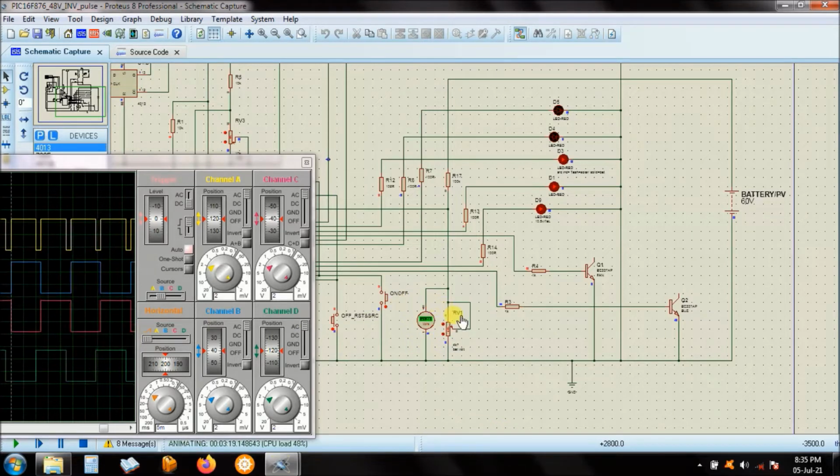Right, now I can go down here so that you see how the LEDs behave, slowly going down, using this port. Right now it's at the maximum power point voltage of the module. It will go there in that stage, and then later on, after 3 seconds, it will go into alarm mode.